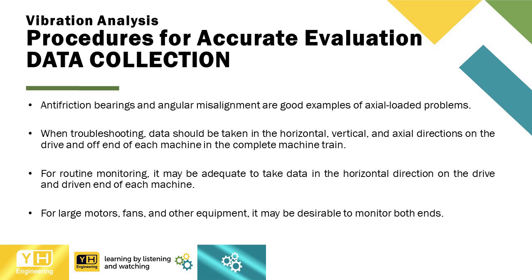When troubleshooting, data should be taken in the horizontal, vertical, and axial directions on the drive and off end of each machine in the complete machine train. For routine monitoring, it may be adequate to take data in the horizontal direction on the drive and driven end of each machine. For large motors, fans, and other equipment, it may be desirable to monitor both ends.